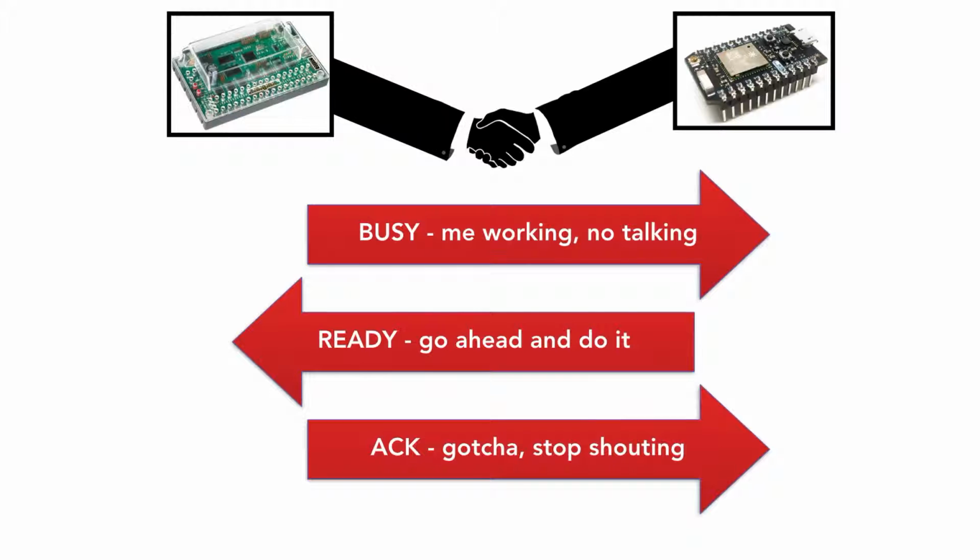To explain this communication in detail, we'll use a so-called timing diagram. On the left-hand side, you can see the bit or data lines. These are the 5 command bits from the Photon to the robot and the ready signal, and these are the lines from the robot back to the Photon. The result lines were originally intended to transmit a color value and are therefore still called col0 and col1. Note that the busy is a low active or inverse line, hence the horizontal line above its name. That means that the robot signals that it's busy by pulling this line down to logical 0. We'll see why that is useful in a moment.